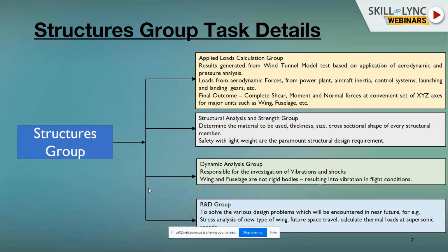Now this is what you apply either manually in Excel, but these days nobody uses Excel, so we do it in Nastran as a solver or Hypermesh. We apply the boundary conditions and loads in Hypermesh. So this is the way it is done. Earlier, till 2014, even Hypermesh was not approved for structural analysis. Before 2014, all the aircraft models were prepared in Patran. Now these days the companies are okay with Hypermesh, because earlier they did not have certified data from Hypermesh.